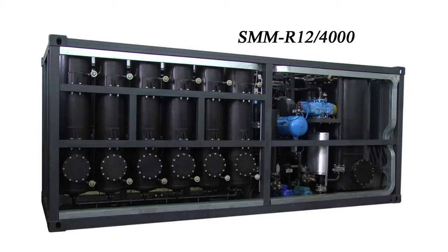Reactivation waste products are accumulated in a special collector vessel for draining. When the reactivation cycle is complete, the system is again ready for oil regeneration. The sorbent in the system can be reactivated up to 300 times, which constitutes 1.5 to 2 years of operation until it needs to be replaced.